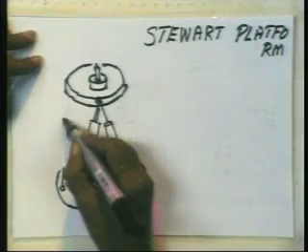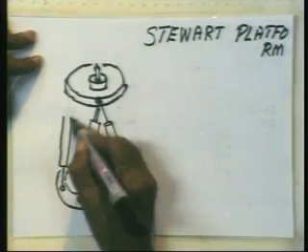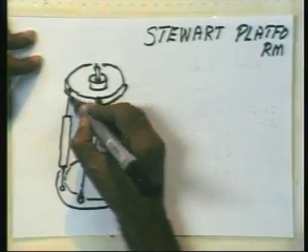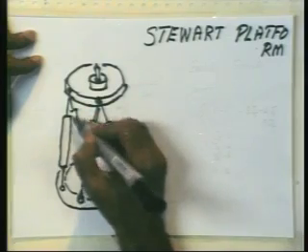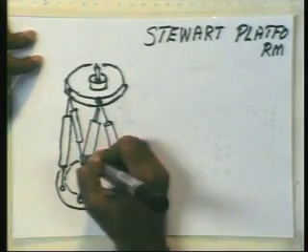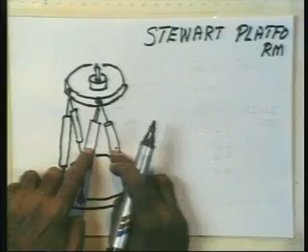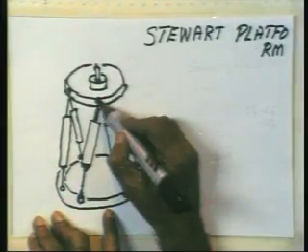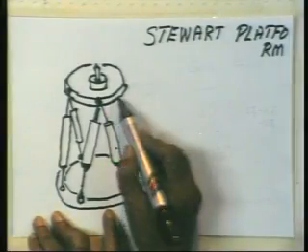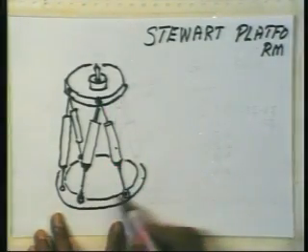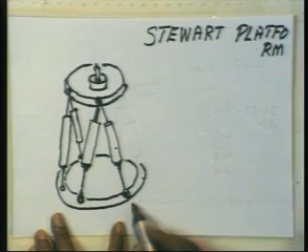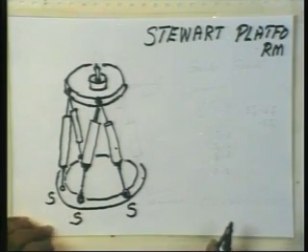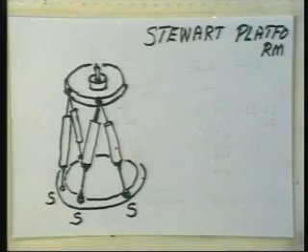Here is another actuator. And this fellow is also pivoted here in some form. There is another actuator. So you see two pairs, two actuators. At the top, both the piston rod ends are connected to a specific joint on the top disc. At the bottom, they are separately connected. This is a ball and socket joint, a spherical joint. I will call it S at the bottom. What is known as a spherical joint is used.